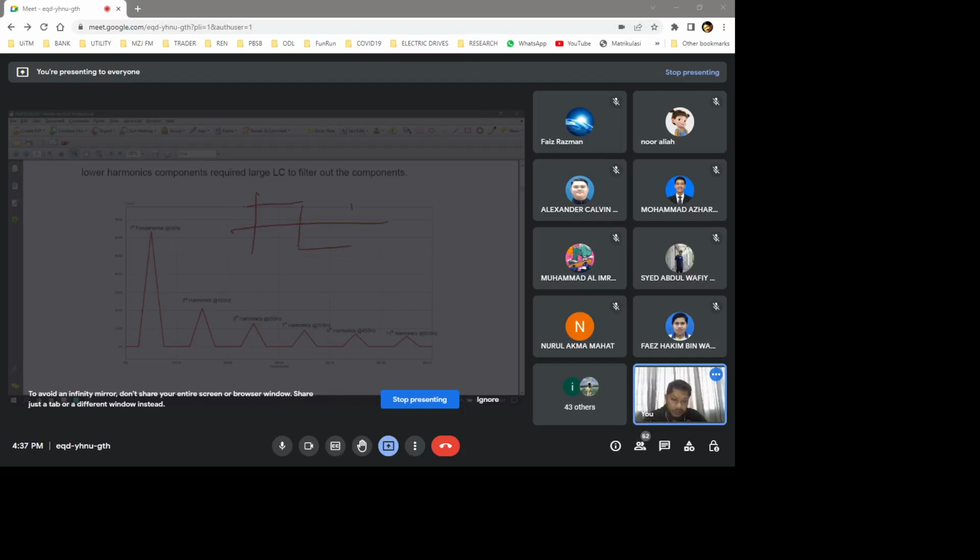If you look at the harmonic spectrum, you're going to see that this square waveform comes from the fundamental 50 Hertz with a certain amplitude, which is V1 peak, and then it adds the third harmonic with a certain value of V3 peak, and the fifth harmonic. So this square waveform is actually made from sinusoidal waveforms at different amplitudes and different frequencies: third, fifth harmonic.